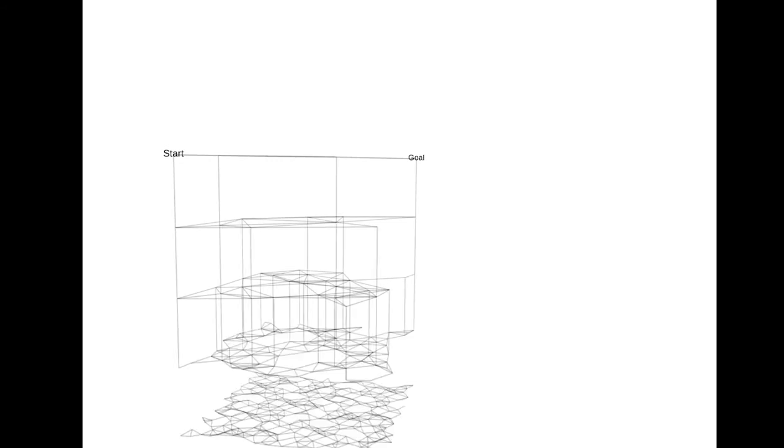The top layer is a very sparse roadmap. The next layer contains a denser roadmap. It contains all the configurations from the previous layer and adds additional configurations. We connect the nodes from different layers, but at the same configuration, with zero-cost vertical edges. We continue this process, creating denser and denser layers.